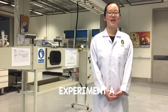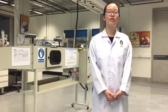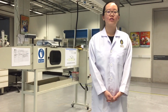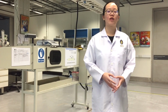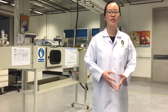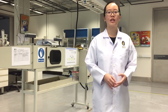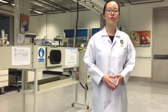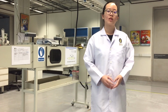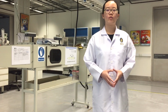In sub-experiment A, we investigate the influence of air temperature on the drying rate of a wet solid. To carry out this experiment, we need the air velocity and surrounding humidity content to be constant and the heater power to have a different air temperature. The air velocity was constant at 10.4 meters per second. The heater power was turned to point A, which is 33.1 watt.